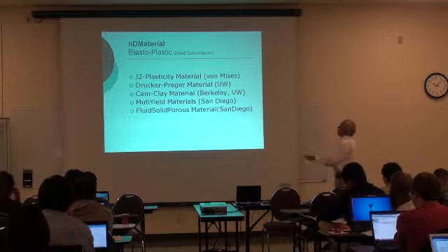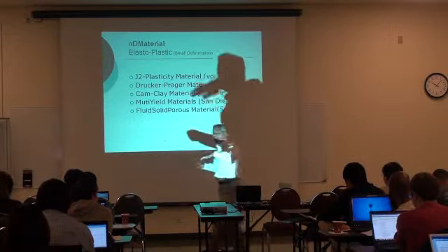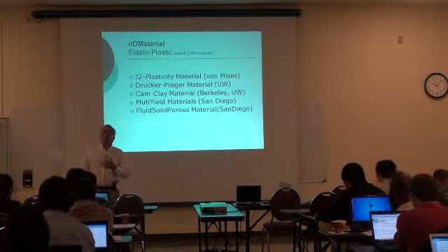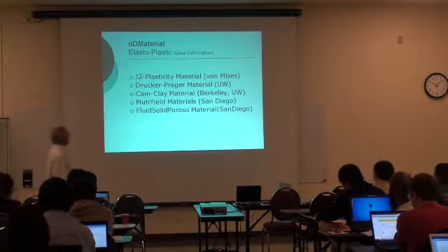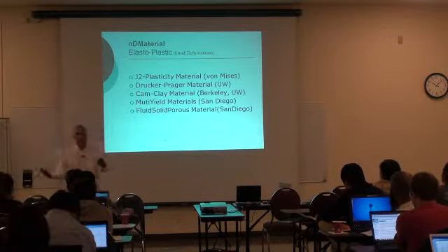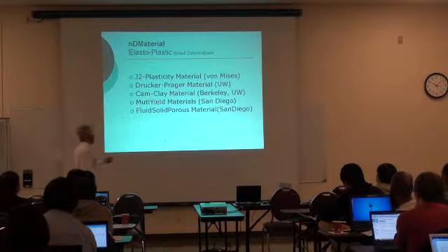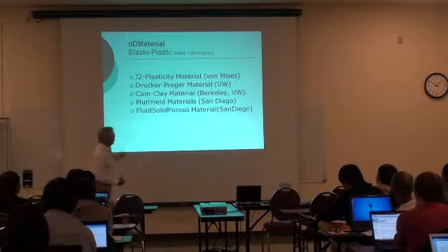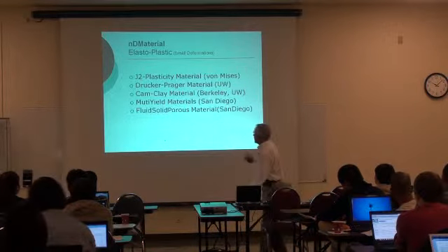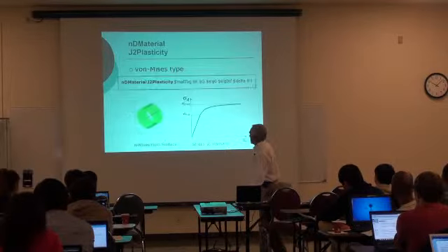And then you have the multi-yield materials that were developed for geotechnical engineering in the United States, made popular in the United States by Prevost. And then Elgamal has been working a lot with these models. And actually, if he was here yesterday, I'm sure that he talked a lot about the multi-yield materials. And he also developed what is called a fluid solid porous material that allows to connect. It's a trick that he uses in order to impose what is called the incompressible condition. I don't suggest to use that too much.